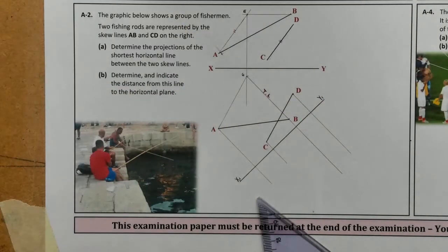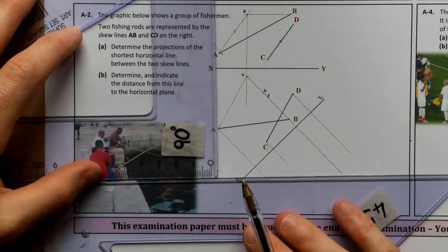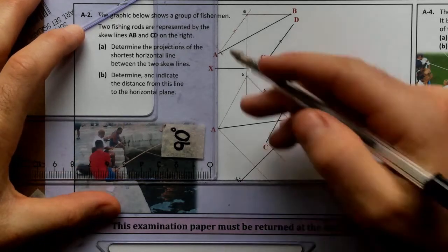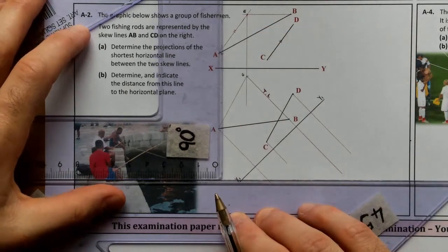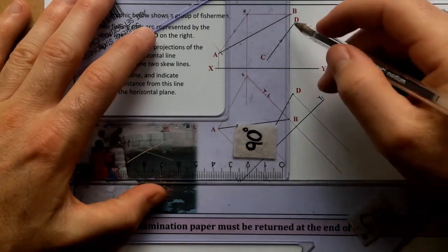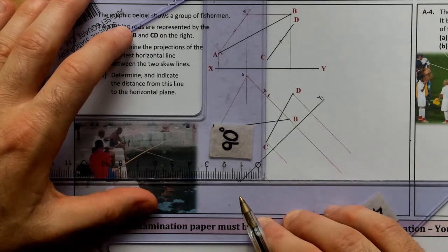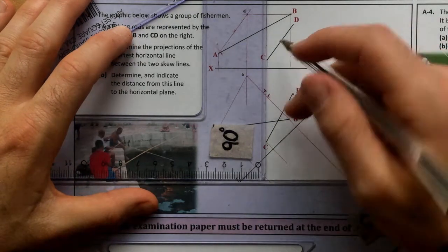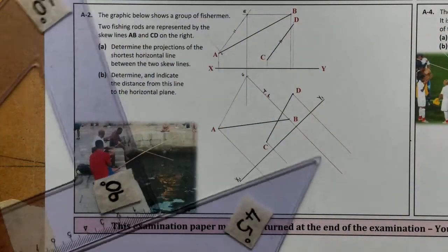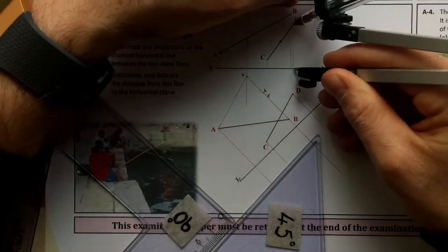So just to be 100% accurate, what I'm actually going to do, I'm going to line these up and take that height there. That's the height to be. Just want to get the exact vertical height. As you can see, I'm just lining them up with the plan views underneath. So the heights I want are here. You can see I put them in very faintly. So for the first one, I'm just going to take D there.